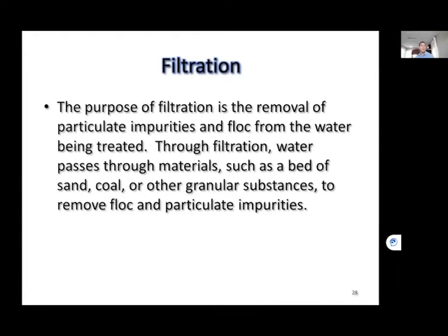Filtration. The purpose of filtration is the removal of particulate impurities and floc from the water being treated. Through filtration, water passes through materials such as a bed of sand, coal, and other granular substances to remove floc and particulate impurities. Filtration to me is one of the most important processes at the water treatment plant. And really your coagulation, flocculation, sedimentation processes are to set up the water to be filtered in the best way.